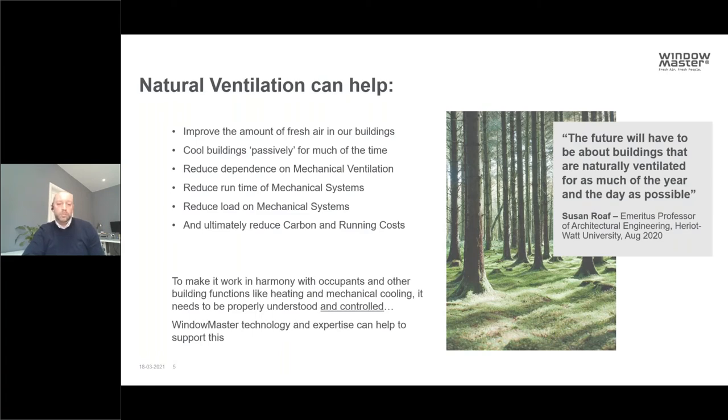By using natural ventilation, we can reduce our dependence on mechanical ventilation systems. We can help to reduce their runtime by naturally ventilating the buildings most of the time. We can use intelligent strategies like night cooling to reduce the load on those mechanical systems should they have to come into play, to take the peaks off temperatures in summer. But ultimately, natural ventilation can help to reduce carbon and the running costs of buildings.